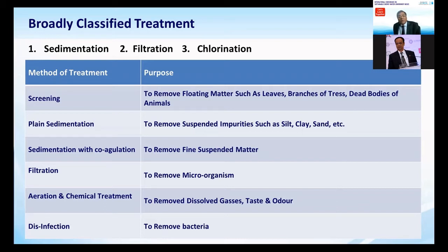When you do the chlorination of the water, then you have to do the dechlorination through activated carbon filters or sodium metabisulfite or calcium metabisulfite.